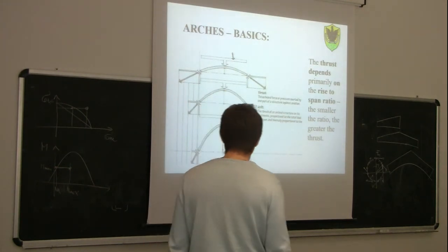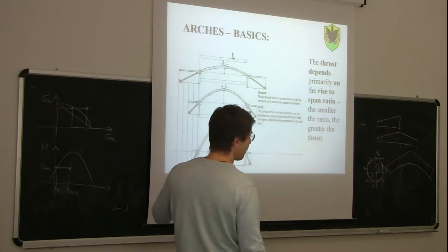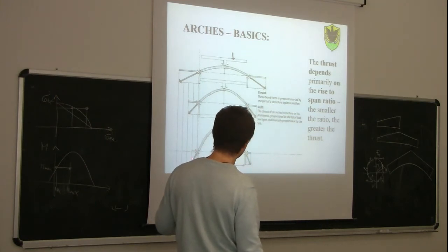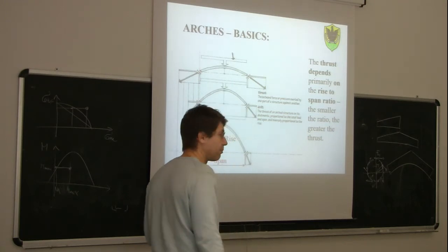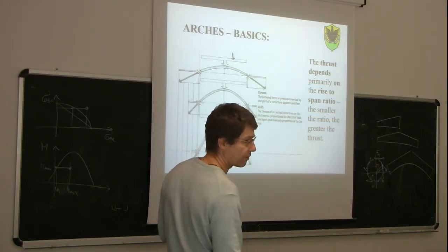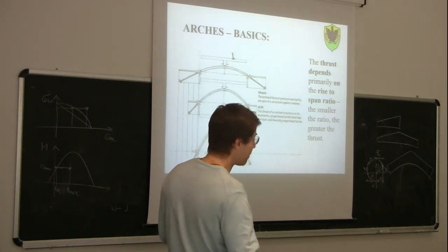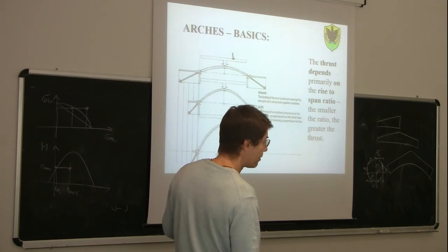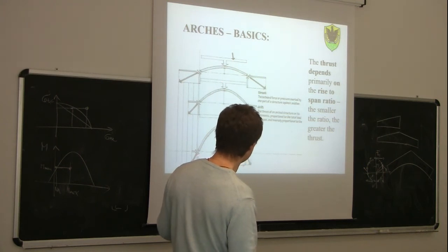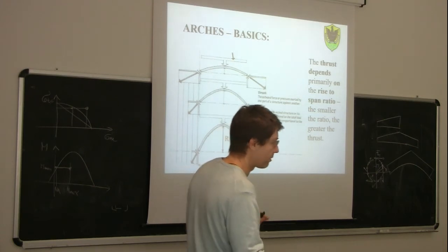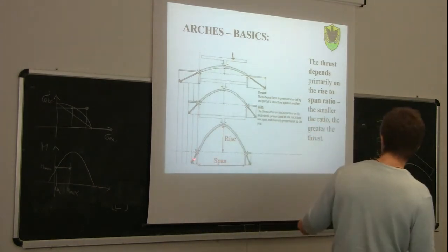So from the equilibrium on the same vertical load, as you can see, the vertical component of the reaction is the same in all three cases. So there is no difference in terms of vertical component. It could have been different, because from the equilibrium, the sum of these two forces must be the same as the result of the vertical load, which is the same in all three cases. So this vertical component is the same.